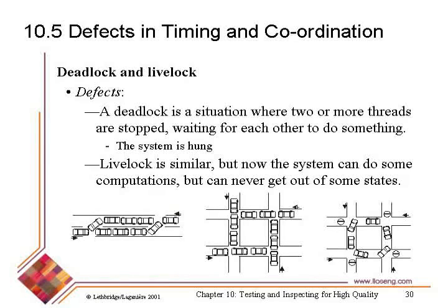Now, this is actually not called deadlock. This is called livelock. So deadlock is the situation where all the traffic grinds to a dead halt and can't go anywhere. Livelock is where some traffic can keep moving, but it can't go where it wants to go. It just keeps getting stuck in a loop and can't actually move.